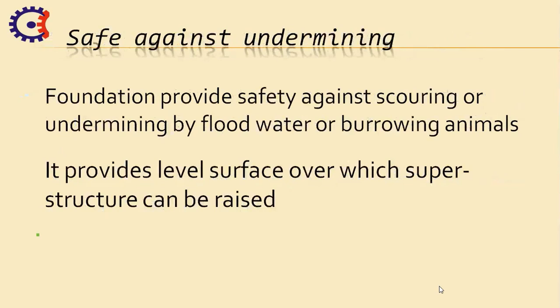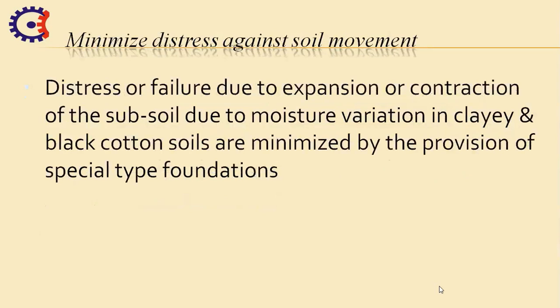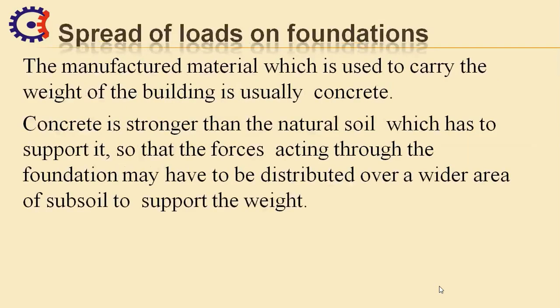Safety against undermining. Foundation provides safety against scouring or undermining by floods, water. It provides the level surface over which the superstructure can be built. This part we earlier discussed. Then minimize the distress against soil movement. Distress or failure due to the expansion or contraction of the subsoil due to moisture variation in clay and black cotton soils is minimized by the provision of a special type of foundation.